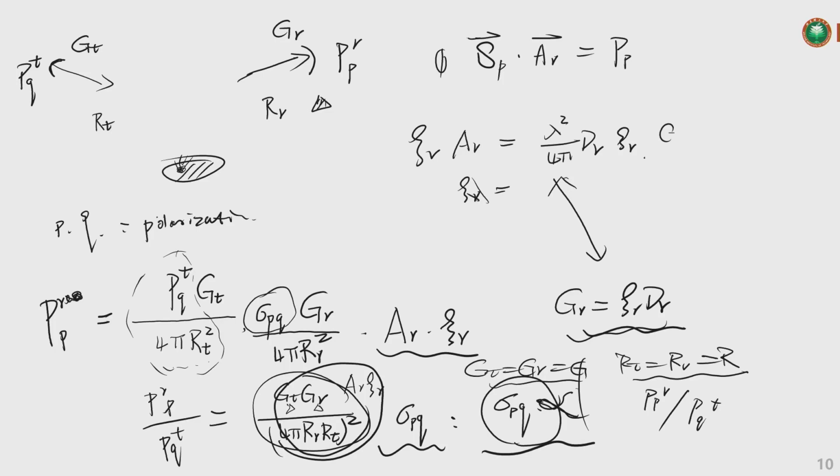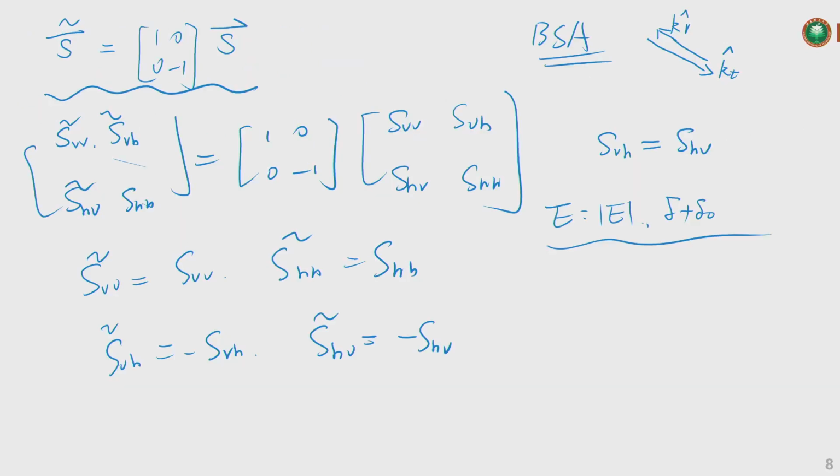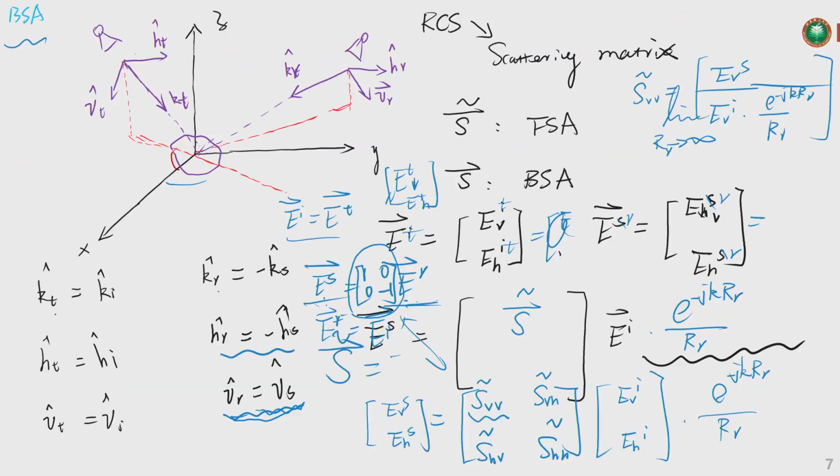But what we can do is definitely related to 1 over the fourth order of the distance between the antenna and the target. So this is for a point target. We usually set the detections to be a point here, and we position the target at the origin of the Cartesian coordinate system.